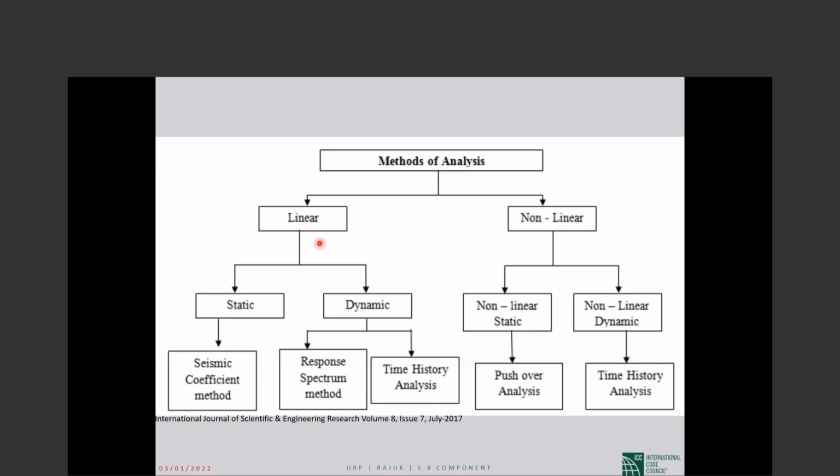The conditions, as we will see later, based on the condition, give us the m value for IO, m value for LS, m value for CP, which means the amount of damage that is acceptable in these deformation control parameters at IO, LS, or CP level.